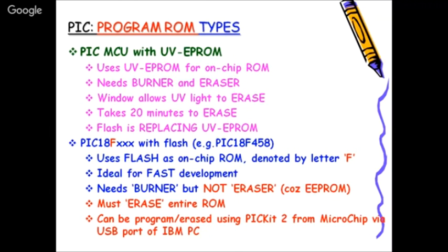The pen drive itself is an embedded system. A pen drive is not only memory. It's not only EEPROM or flash memory. It has flash, and there is a microcontroller inside it, with the driver circuitry that is used for accessing that. So there is a flash memory, and there is a controller and complete driver and all that electronics. So pen drives themselves are a complete embedded system.